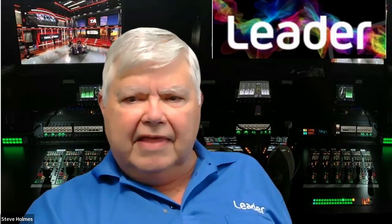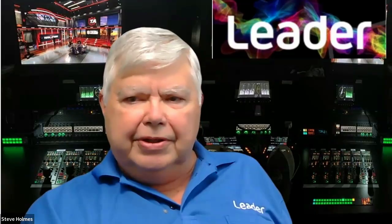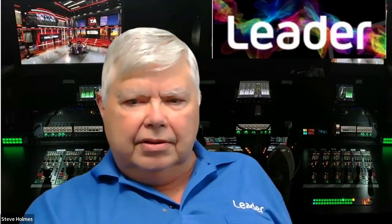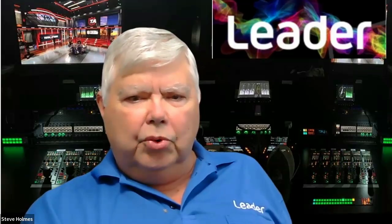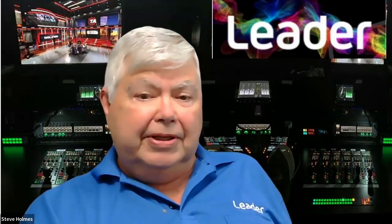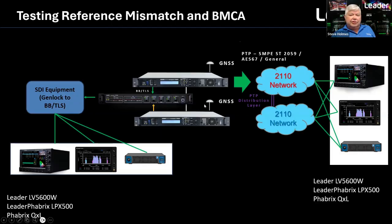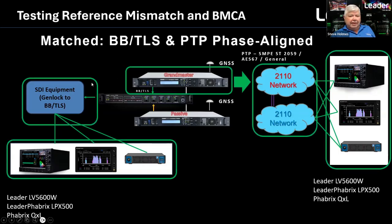And what I mean by that is we can get into states where you could have a PTP failover, but your baseband signals won't fail over, and you can end up working off of two different SPGs.